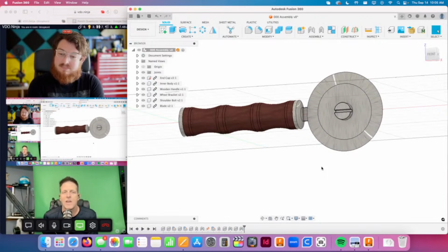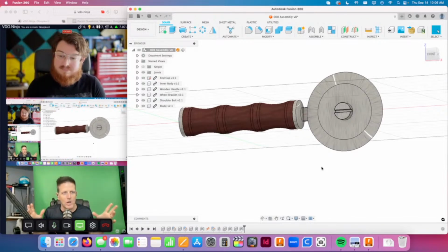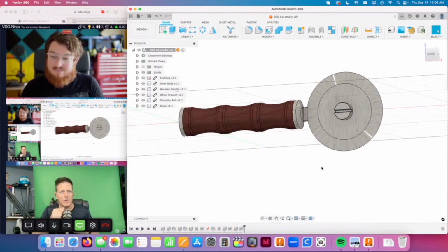But oftentimes, instead of making a change, saving the mesh, slicing it up, and printing it out, I'll create an array of say 10 different holes of varying diameters, print it out at once, and see which hole is best for the fitment of whatever application, whether I'm trying to put a pin or a screw or a bearing in there.